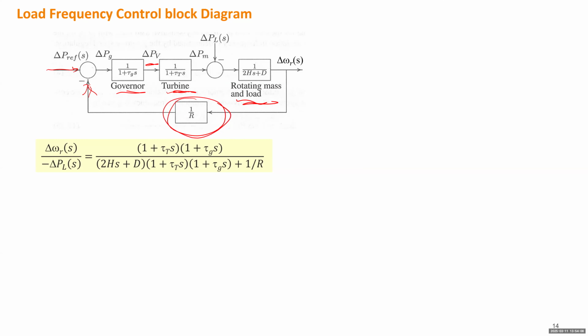So that will close this loop and make it a negative feedback. It will form a droop control. The R here indicates the slope of the droop control. The smaller R means you have better control, because this feedback signal will be multiplied by 1 over R. So if you take a very small R, oh, sorry, I didn't distribute the slides. Yeah, but we haven't gone to the new slides yet.